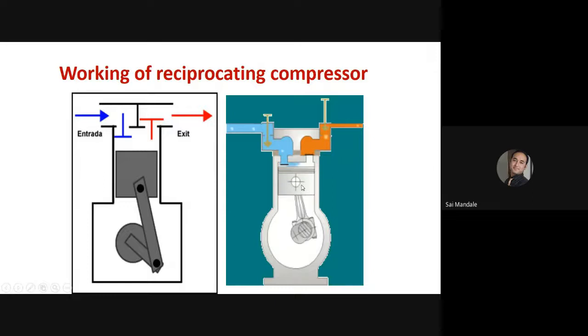Let me explain the motion produced by each and every component. Piston always reciprocates inside the cylinder. Then the connecting rod is oscillating. The connecting rod is always subjected to oscillatory motion. The crank is subjected to rotary motion. The crankshaft is subjected to rotary motion.